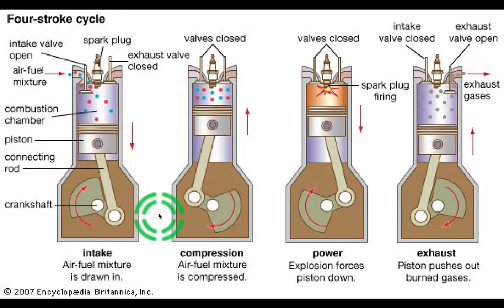Then the first stroke, this is what you call your intake stroke. Air-fuel mixture is drawn in. How is it drawn in? Because this is like a syringe, it's a huge pump. When it comes down, it obviously has to suck in the oxygen. Now what happens? Compression is your second stroke.